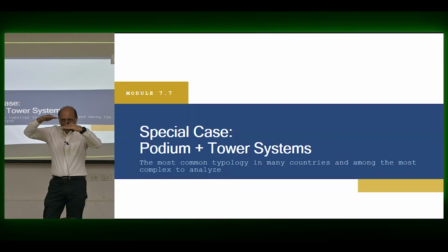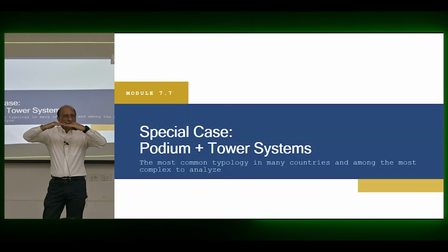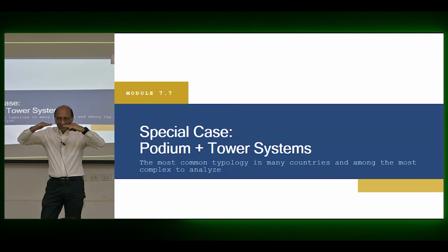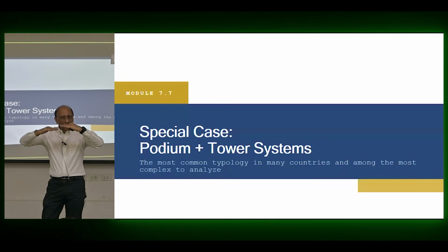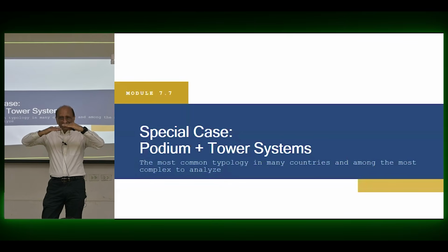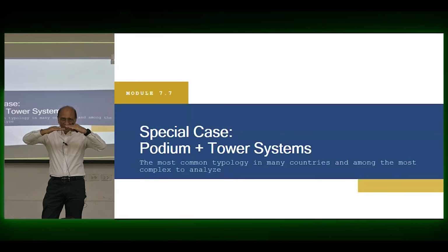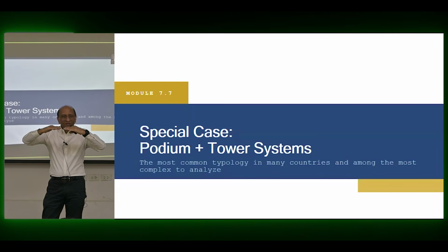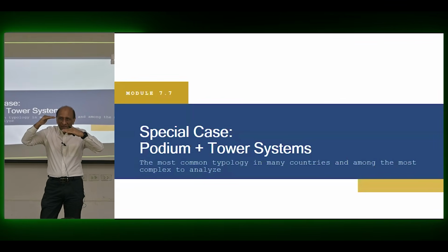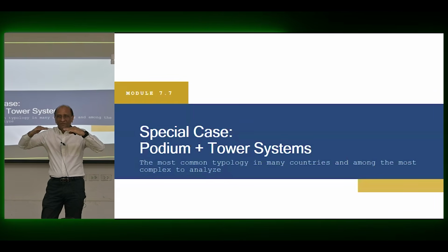So now the floors which were originally level are no longer level, this one now going down. So that means suddenly this floor, which was the same when you constructed, now this tower portion starts to go down because the soil is now settling. And then you either break it or you make it tilt. You have an expansion joint. Expansion joints have another problem because the floor is not level. So you have to make all these calculation corrections beforehand to actually make the tower longer, higher than the podium, so that when they settle, then they are at the same level.